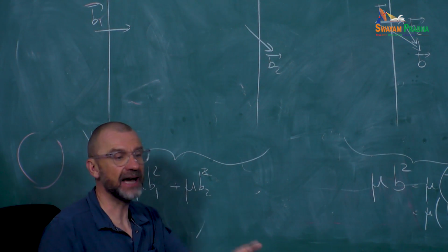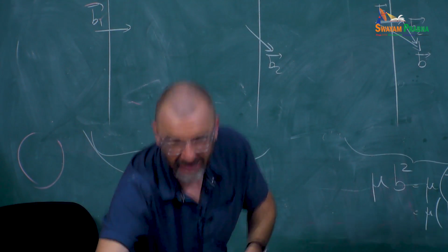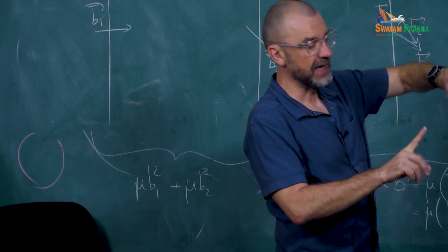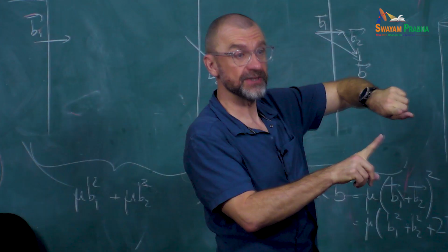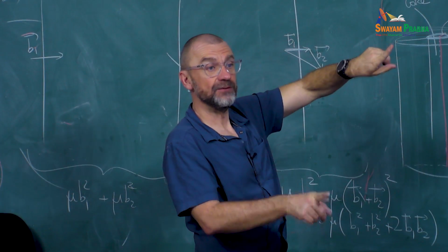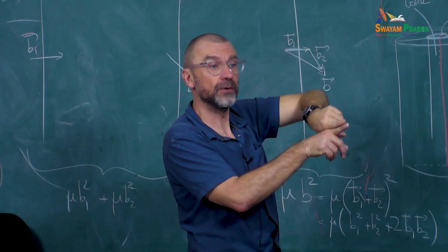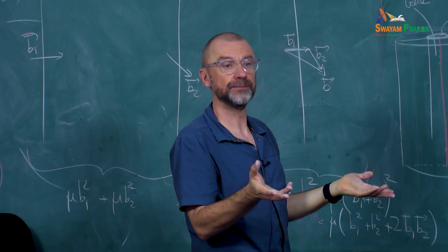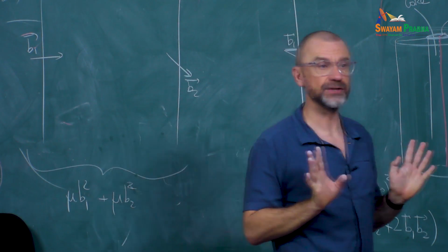So you can extend that, and it qualitatively works. It's called Frank's rule. If I have two dislocations, if the dot product of their Burgers vectors is positive, they repel each other because they don't want to join. If the dot product is negative, then they attract each other because they want to form a junction, and that's called Frank's rule. And it comes just by the fact that the line energy is proportional to B squared.